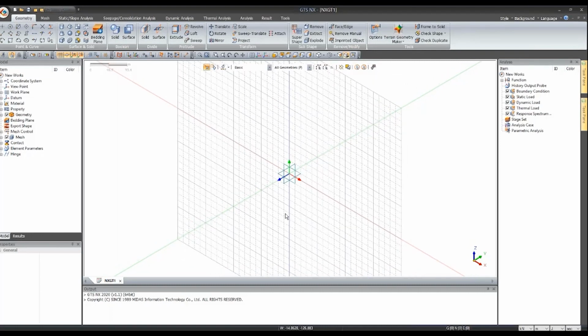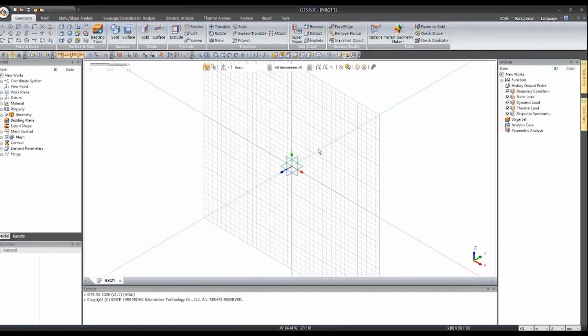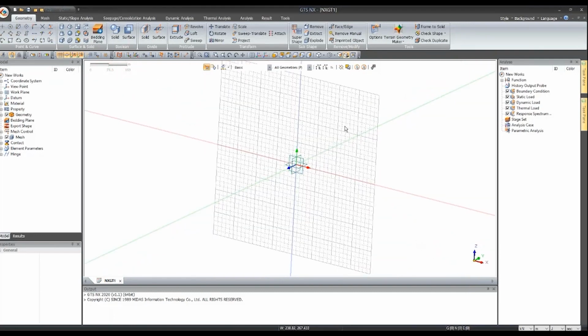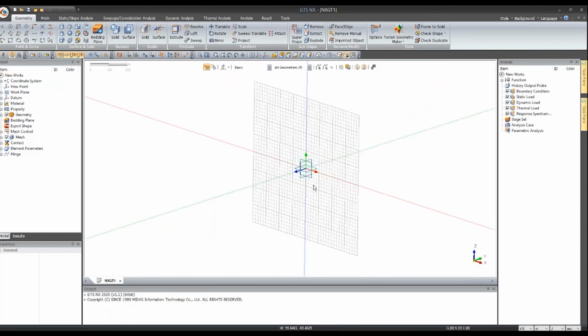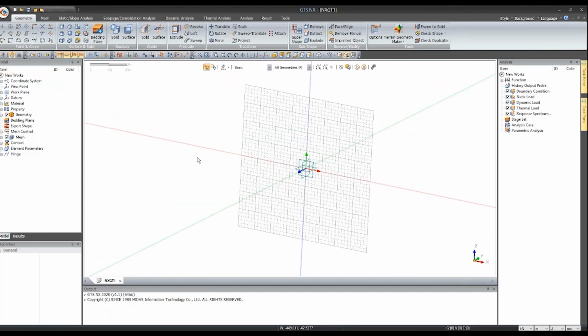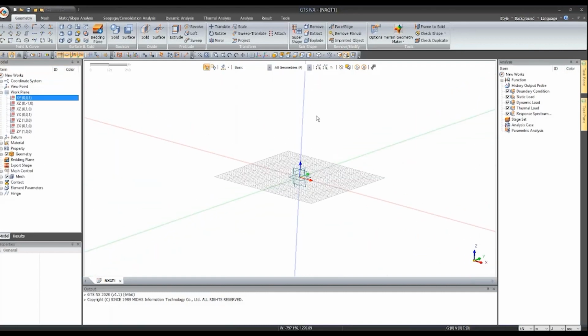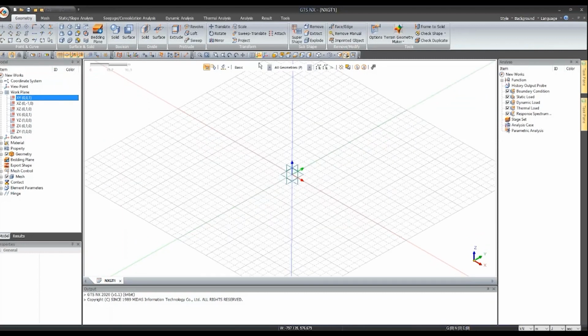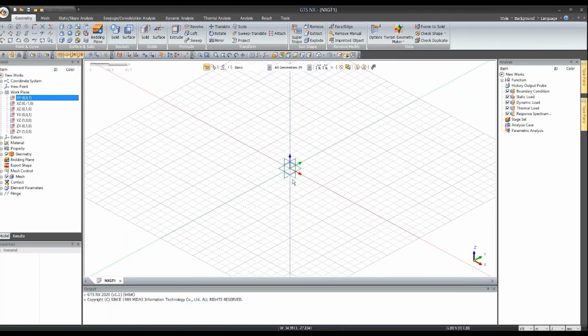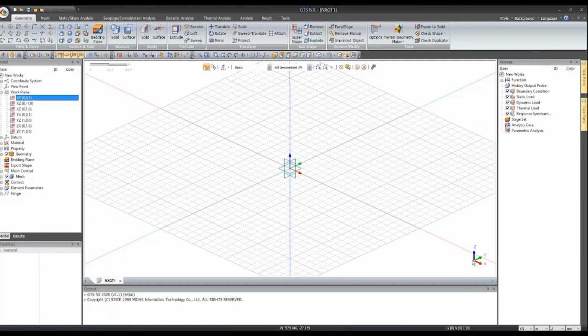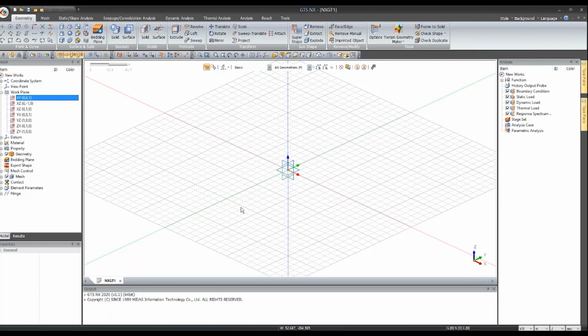So now we went for 3D modeling, and we have the interface in front of us. This is the work plane, and right now it is in a ZX plane. Let me shift to the XY work plane. So this is the horizontal work plane for us. In terms of settings, you can see the gravity direction is set, that means minus Z is the gravity direction. And as I said, the building, we are going to import it from MIDAS Gen.